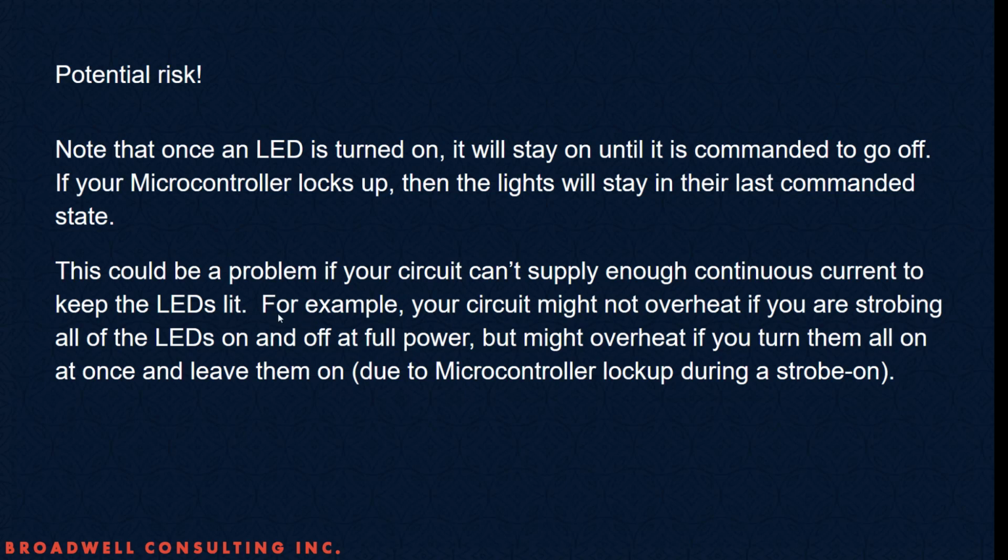So for instance, perhaps you have a whole bunch of LEDs that you're using like a strobe light. You blink them on for a fraction of a second, then turn them off for a relatively long period of time, allowing your circuit to cool. If for some reason your microcontroller locks up during the period that you're on, the lights will stay on until they're commanded off, which will never happen because the microcontroller is locked up. At this point, the system will be running at full power and 100% duty cycle, which potentially could exceed the capability of your circuit if it's not designed for that.